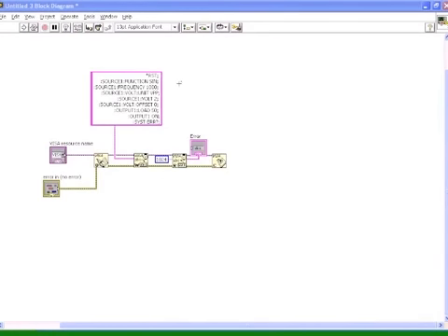When you create a string like this, you need to put a leading colon in front of the root commands that follow *RST. This indicates to the parser that you're starting a new root command. The 33522A is a 2-channel box, and you designate channel 1 and channel 2 by using SOURCE1. This is the root command in this instance. If I put SOURCE2, I'd be talking to channel 2.